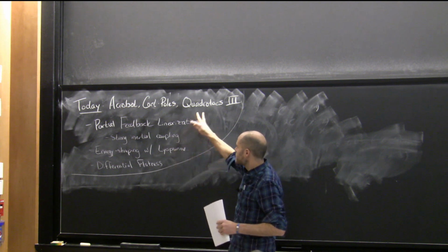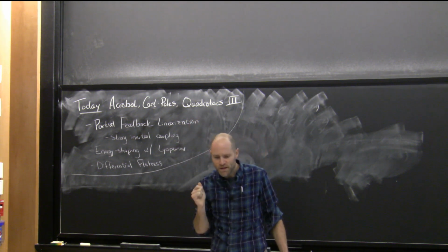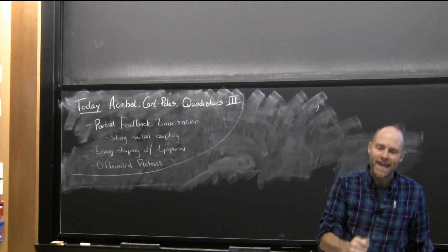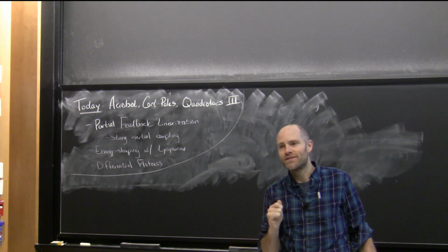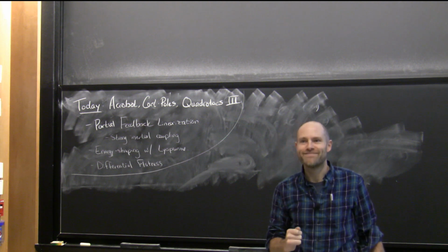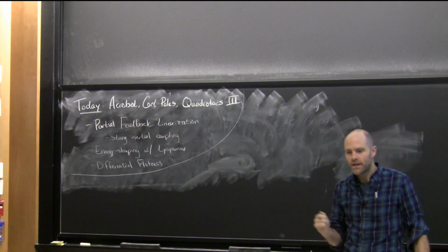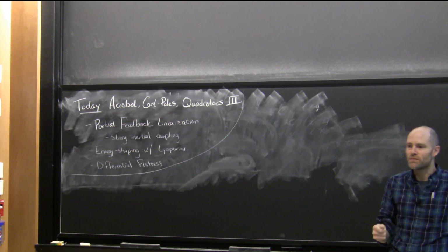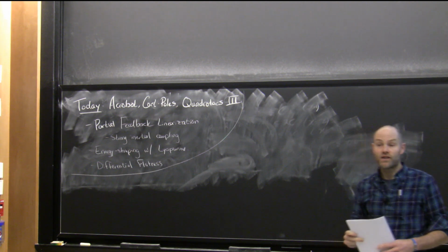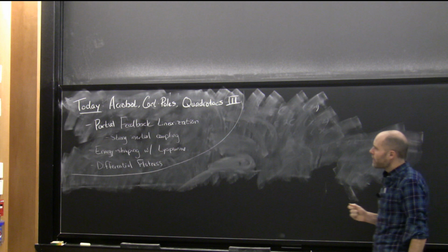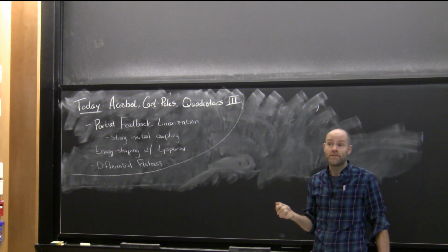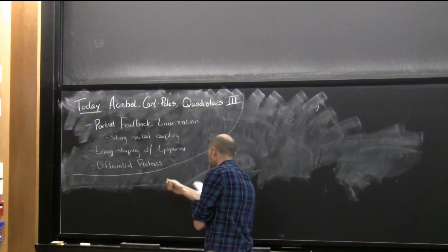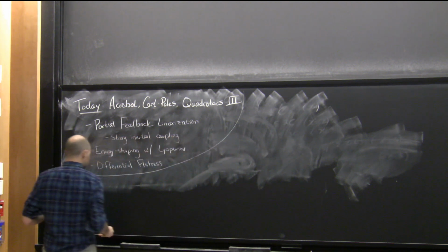So that's the big theme today: roughly speaking, if you have n degrees of freedom and you have m actuators, you get to control m things. We're going to try to make that formal. Certain conditions have to apply to make sure that those m things you've chosen are controllable, are coupled to your actuators. But there's a couple different ways that manifests and gives us the ability to write controllers or write planners.